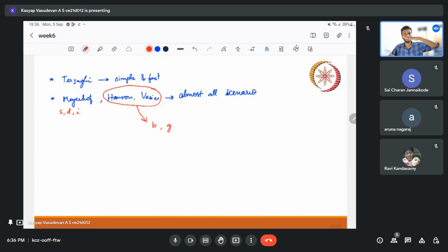So if the base of the footing is a little inclined, they take care of that. And if the ground above the footing is a little inclined, we also have different factors. So our factors will be like SC, DC, IC plus BC, GC. If we have all these scenarios, we can take account of that.